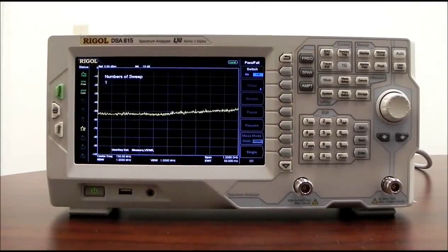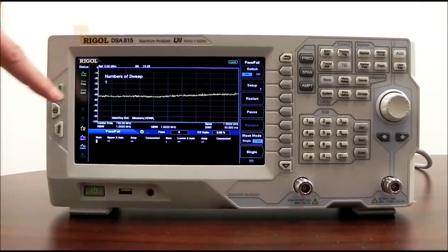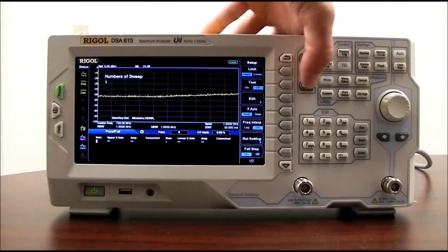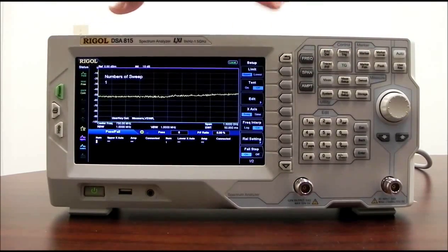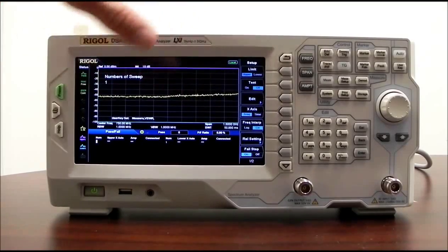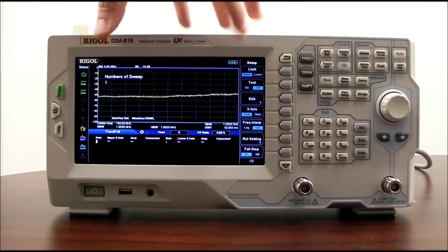There's also a pass-fail area. Pass-fail is useful for a number of tests. Okay, so I'm just going to enable pass-fail, and you can see that when we enable pass-fail, we actually have criteria down on the bottom. We can set up pass-fail. With the DSA815, we have 2 limits that are enabled. One, we can enable upper, or we can enable lower. Upper, we cannot exceed upper, or it will be a failure. Lower, we cannot exceed lower, or it will be a failure. So they are more like a window, upper and lower, around a certain value. You can use this to edit and actually build around a particular channel.